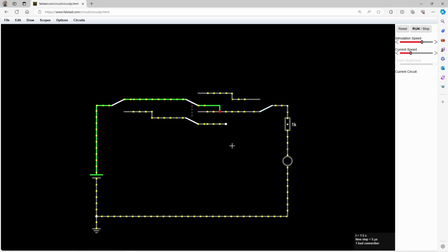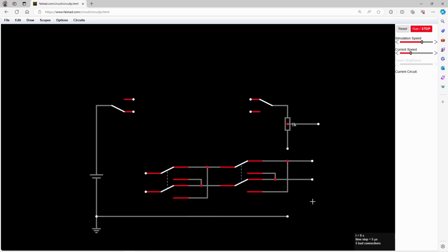So you can see we've got a three-way switch using two SPDT switches and one DPDT switch, which is N-2, N being 3 switches in this case. With 4 switches, we would just repeat this architecture as we have 2 inputs and 2 outputs. And I believe this would be a generalized solution for multiple switches where we have 2 SPDT switches. So these connections would go down to here, and these 2 connections would go to this switch here, and then we would be able to toggle any of these switches to toggle the LED on or off.